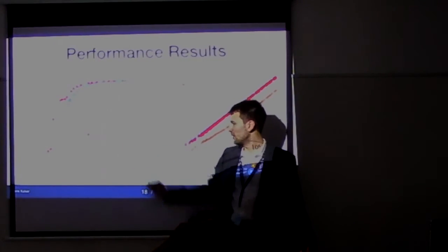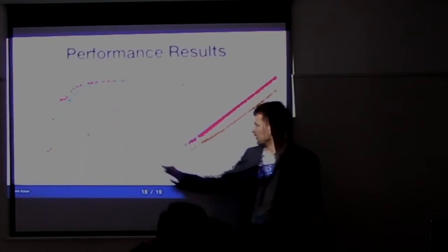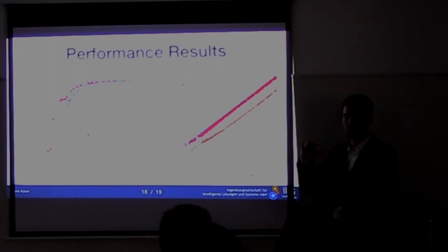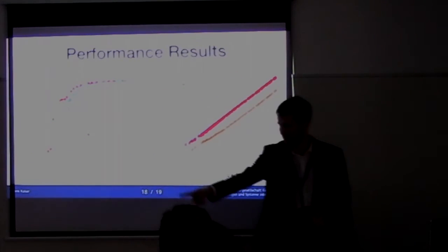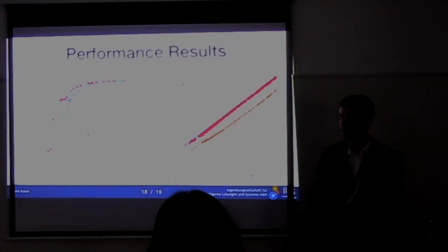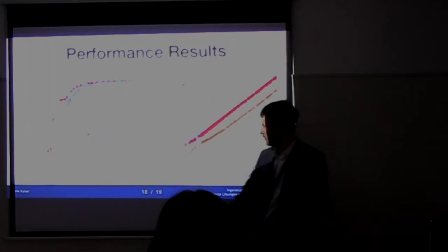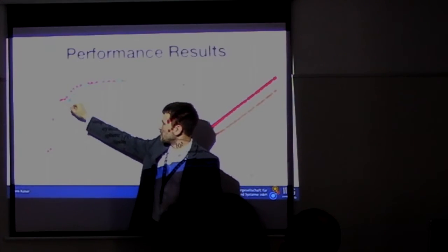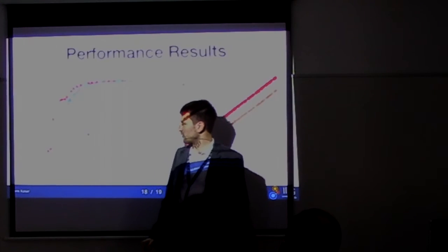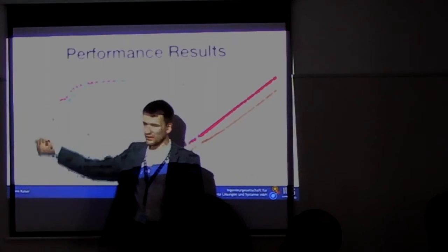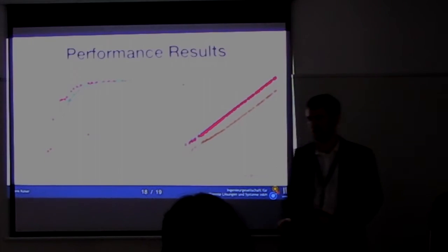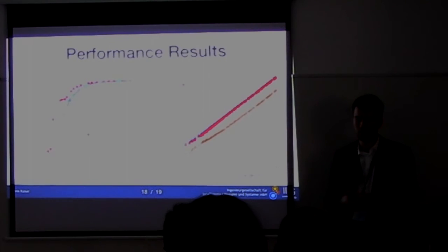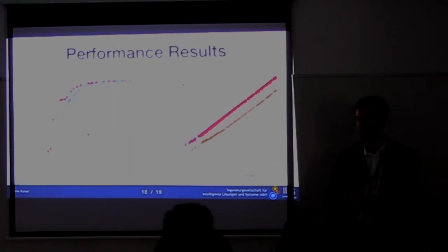I think cylinder, sphere, and so on are clear. The simple connector that is described here is just some cylinders put on top of each other, so that it looks like the connector which we use for the electrical power. And as you can see here, with about 1,000 tetrahedrons, we already get about 98% volume accuracy, which means that about 1,000 tetrahedrons are pretty good to get a good approximation of the original geometry.